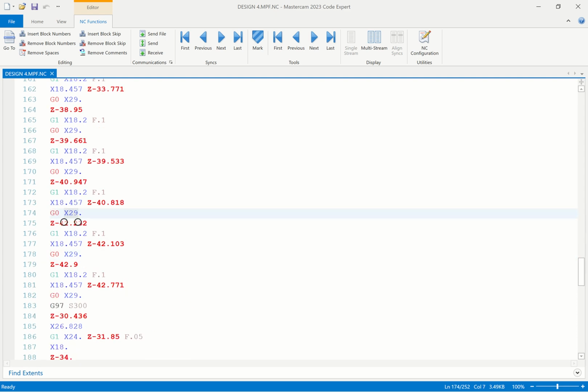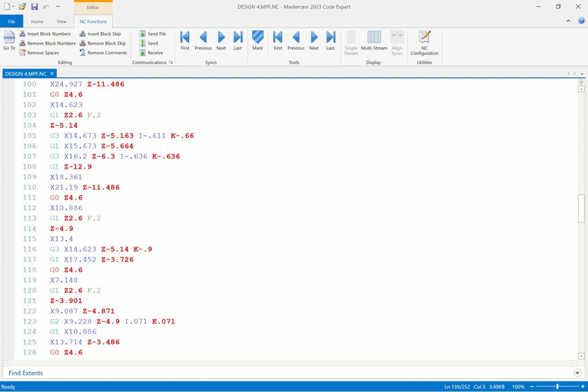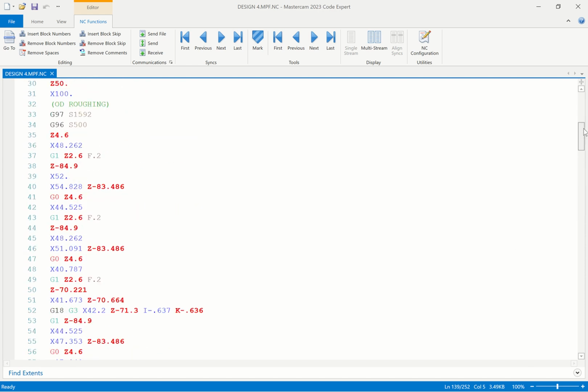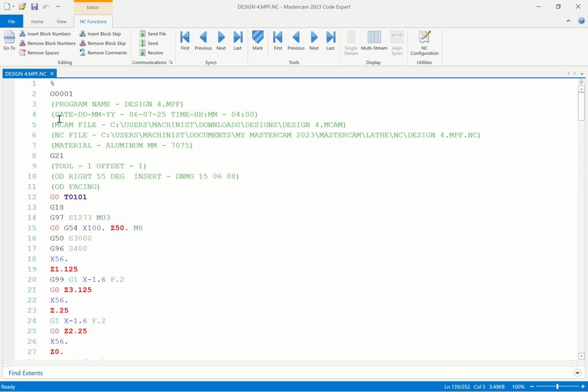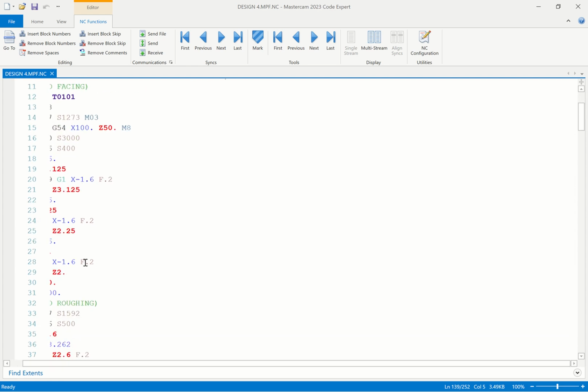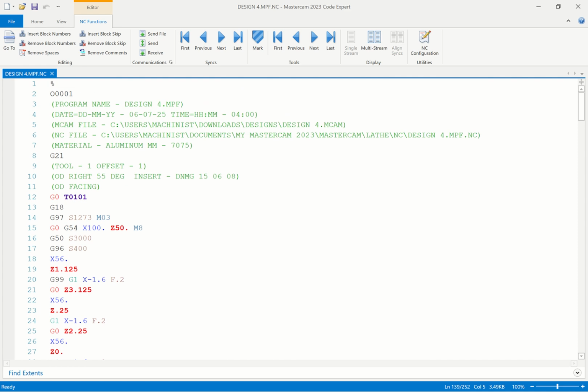So you need to understand the G code before you proceed to program. This is what I require to put on the machine, so the machine can now run and cut the part. This program can run on a GSK machine, Haas machine, Siemens machine, Fanuc machine, unless a syntax error comes when you have not picked the correct controller, or you have not checked the part program. Once you program, you need to check the part program in case of any error, somewhere you didn't do the setting well in the software. You need to check those parameters.